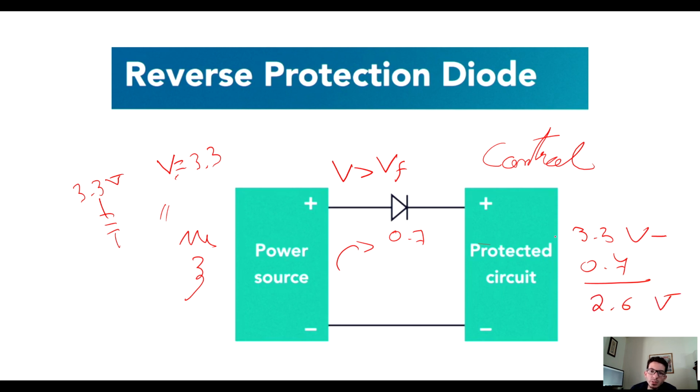So that's why when you read your voltage with a multimeter at certain parts of the circuit after the diode, your voltage is going to be less than the power source. So in that case, you need to tune your circuit to have higher voltage. And in this case, if what you need to supply is 3.3 here, then you need to be applying at least 4 volts.